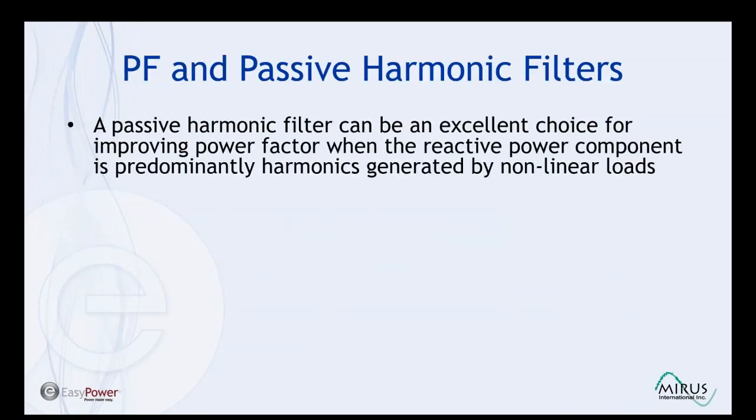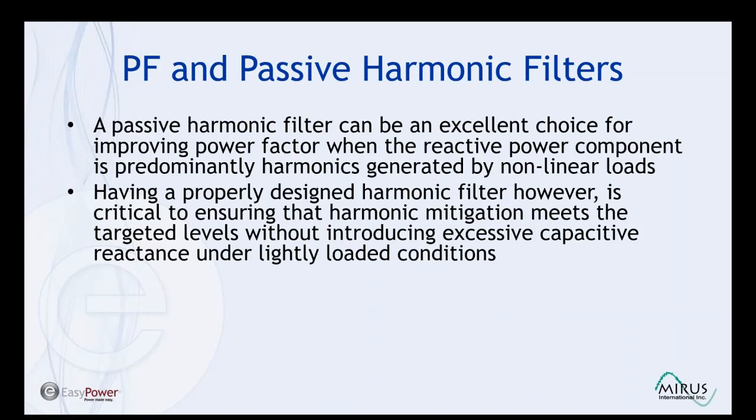Now let's look at the application of a passive harmonic filter. It can be an excellent choice for improving power factor when the reactive power component is predominantly harmonics. But having a properly designed harmonic filter is critical to ensuring that harmonic mitigation meets the targeted levels without introducing excessive capacitive reactance under light loads, or under any load condition, but particularly light loads.